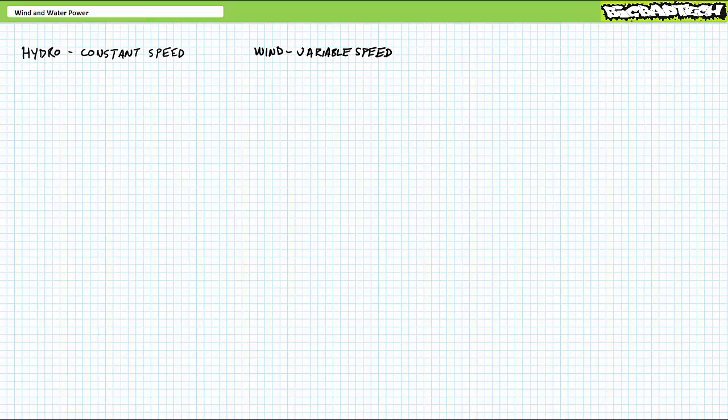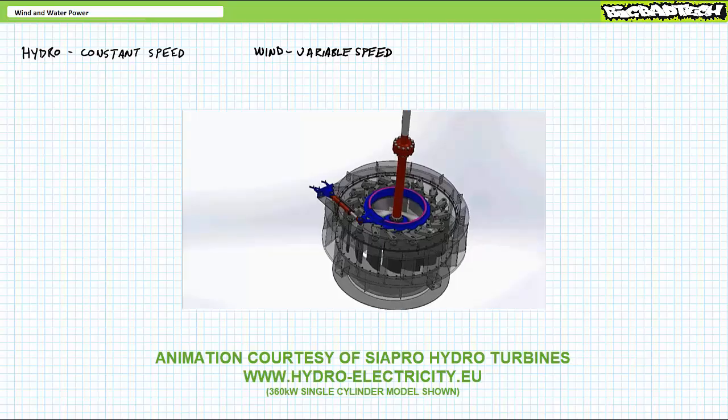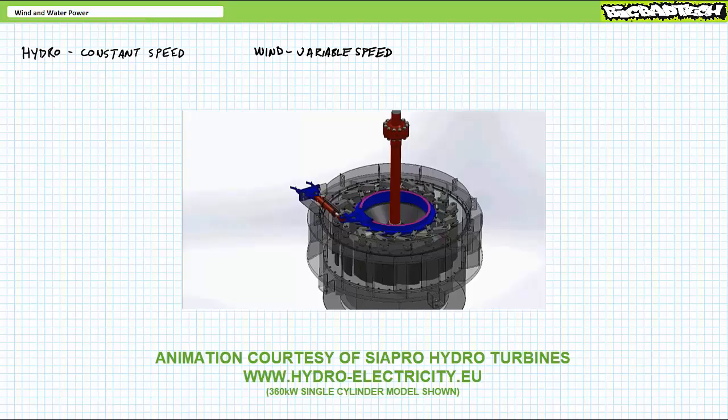Hydropower turbines are different in that rivers aren't known to frequently switch direction, nor does flow rate normally spike up and down. This means hydropower turbines essentially operate by maintaining constant input from an available resource. The management of flow rate is largely performed by opening and closing what are known as wicket gates, using a bull ring and two hydraulic cylinders. As one cylinder extends and the other retracts, they turn the bull ring such that the wicket gates open like Venetian blinds and allow more water in. Conversely, as one cylinder retracts and the other extends, the bull ring rotates in the opposite direction such that the wicket gates close and allow less water in.